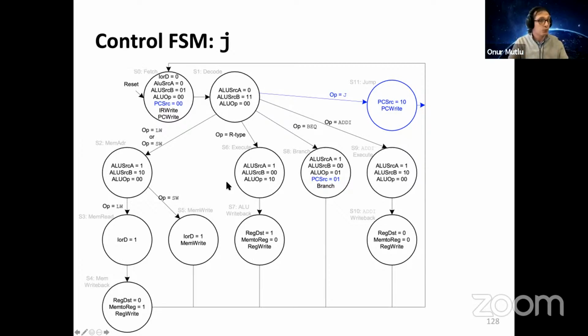By doing some microprogramming and adding maybe some logic so that you can do 1 million loads at the same time. It's very powerful. Basically, you add a loop to this, and you are able to do that relatively easily if you have a finite state machine that's extensible like this. I'm not going to go into the details of it. I'm going to refer you to some other lecture for this.